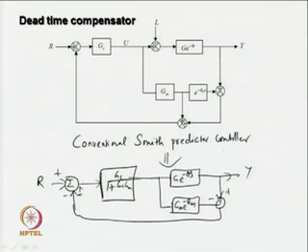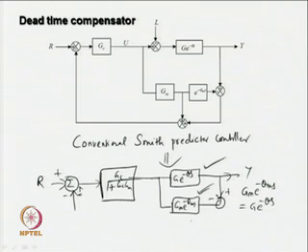Then, what is fed back to the controller? The error signal is made up of the output we get from the actual system dynamics and the system dynamic model. In the event of matching of the two outputs, the output from the original system and that from the model, the signal through this path will be 0. I mean, when G_M e^(-theta_m s) is equal to G e^(-theta s), then what will happen? There will be no signal, therefore I can break this path.